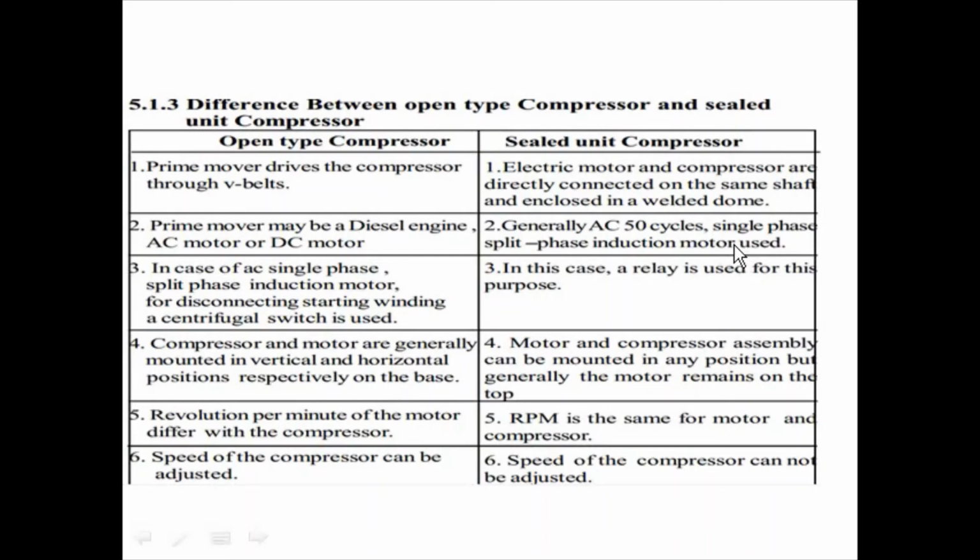Point 3. In the case of AC single phase, split phase induction motor, for disconnecting the starting winding, a centrifugal switch is used. While for sealed unit compressor, in this case, a relay is used for this purpose.